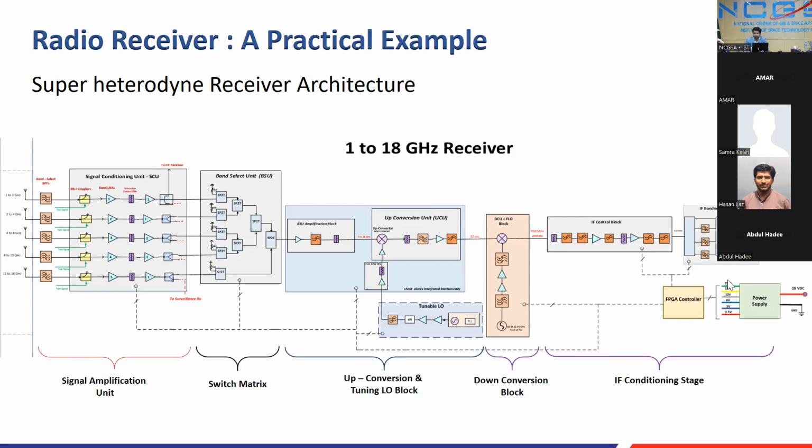Before going into the detail, just to mention, because now we're moving forward: in this whole design, what to take home is that the first two stages, when you are planning a frequency plan, can be your own. You might be interested in L1, L2, GNSS, lower frequency bands, but the first two stages contribute the most towards noise figure.